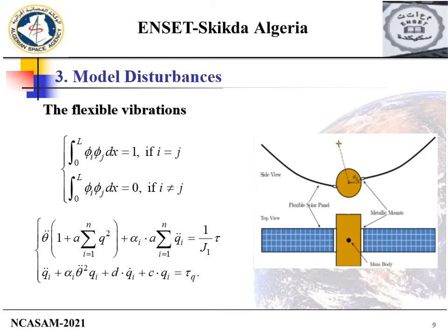After some manipulation and using the orthogonality property of the vibration modes of the beam, one has the first system. Finally, the second system describes the equations of the rotation motion of the satellite and the flexible displacement of the panels, respectively, where the term is defined as the centripetal term, and tau q is the torque of the piezoelectric actuators.